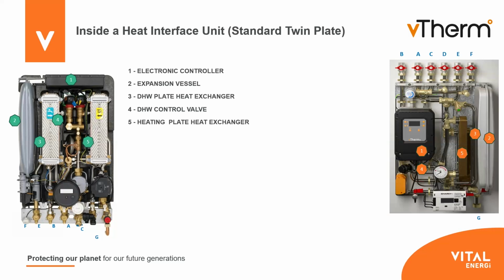You'll have your heating plate with its control valve. And in some cases, because manufacturers are just using a standard controlling valve compared to other manufacturers like ourselves that use pressure independent control valves, they therefore will need a separate additional differential control valve to help with that regulation as pressures are up and down within the circuits.